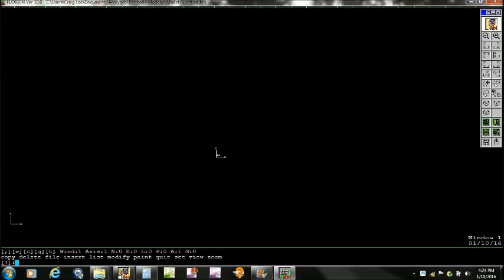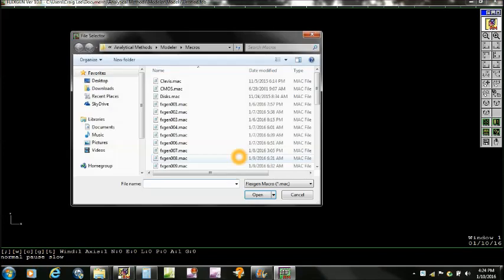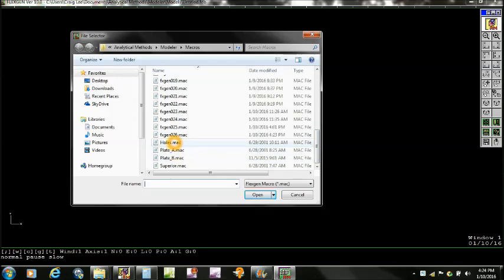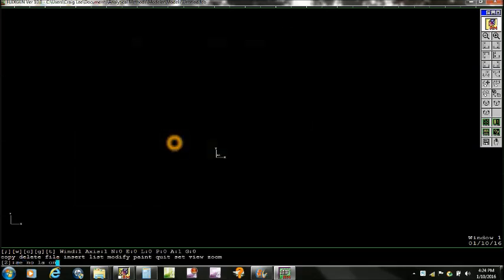So a macro is a series of commands that have been previously recorded that generate the model. So we will go ahead and do a File, Macro, Run, and I'm going to do it in the pause mode so that I can walk through step by step, show you what's going on. So we're going to do holes.mac, and we'll double click on that, and it begins. So the commands are down here in the left-hand corner here.